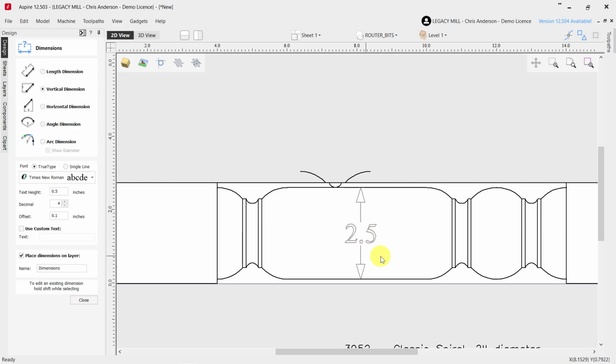So that is our section diameter that the cutter is going to start cutting from. Instead of just slamming the cutter into the material really fast, it's going to start right at the material surface and then work its way into the material at a controlled speed, so we're not accidentally overloading any tools, spindles, or even the machine if we took things too fast.